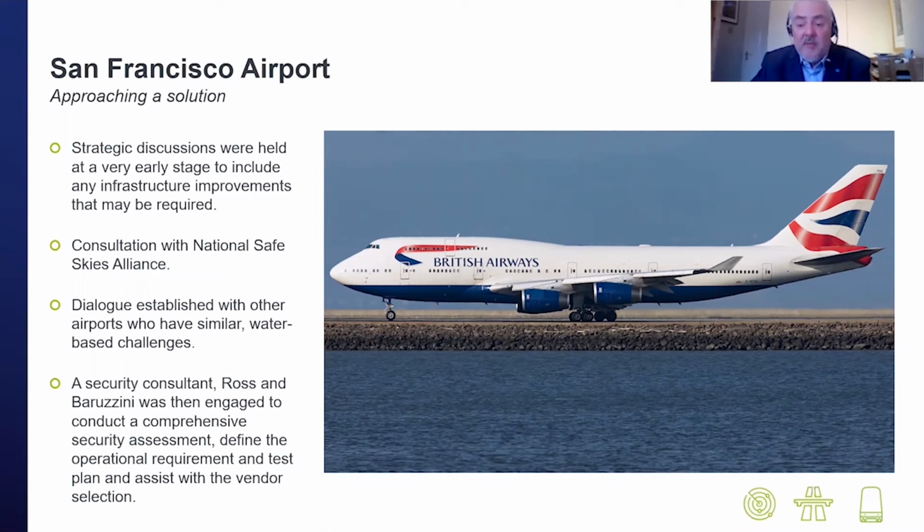So radar is great for monitoring wide open areas from a fixed location, and the thermal imaging cameras and the CCTV cameras make the operator's job of verification very quick and easy. And the analytics from the thermal imaging cameras then act to fill in any gaps that are left by the radar if there's line of sight issues from small buildings, that sort of thing, around the perimeter.